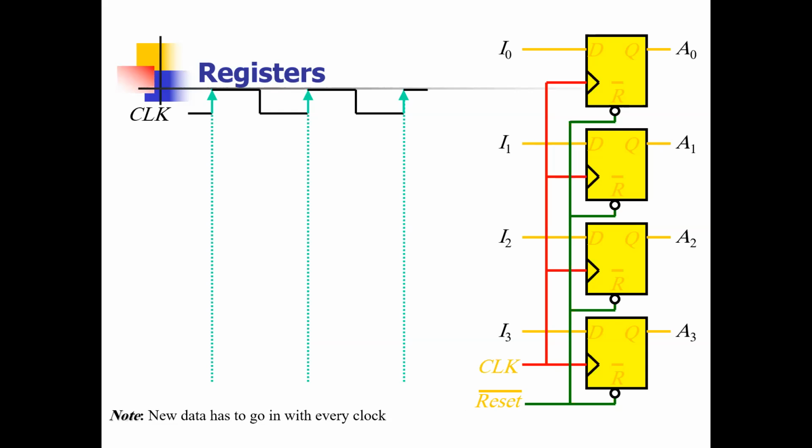So girls, for the direct inputs in registers, we need to connect them because it is very difficult to give the reset to each flip-flop individually; it will take too much time. And you know, girls, in registers we don't always use only a 4-bit register. Sometimes we use a 32-bit or 64-bit register, which means there will be 64 flip-flops. It would be very difficult to give an individual command to each flip-flop. So that's why we have the direct inputs.